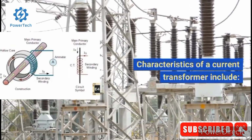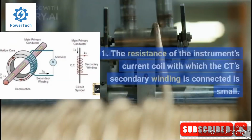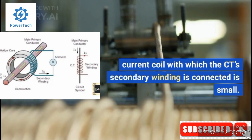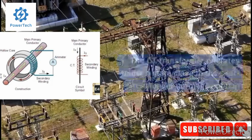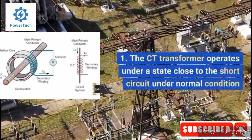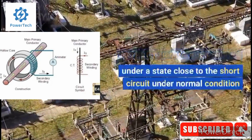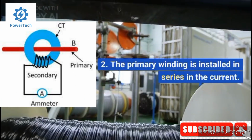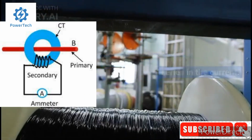Characteristics of a current transformer include: 1. The resistance of the instrument's current coil with which the CT's secondary winding is connected is small. 2. The CT transformer operates under a state close to the short circuit under normal condition. 3. The primary winding is installed in series in the current.